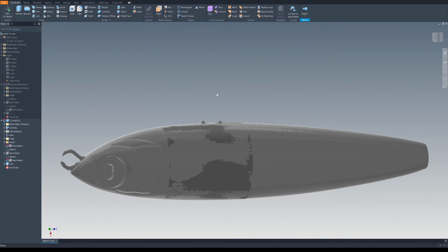Okay, one major difference between reversing with mesh and the point cloud. Now it has the same precision when exported with Creality Scan 4. The disadvantage of using the mesh for reversing in Autodesk Inventor is that when you import the mesh, you need to build it inside of the part. This is the part. So if you need to split your part into small pieces, for example, it's too large for your print bed, it will be more complicated because you are building the model inside of the part.